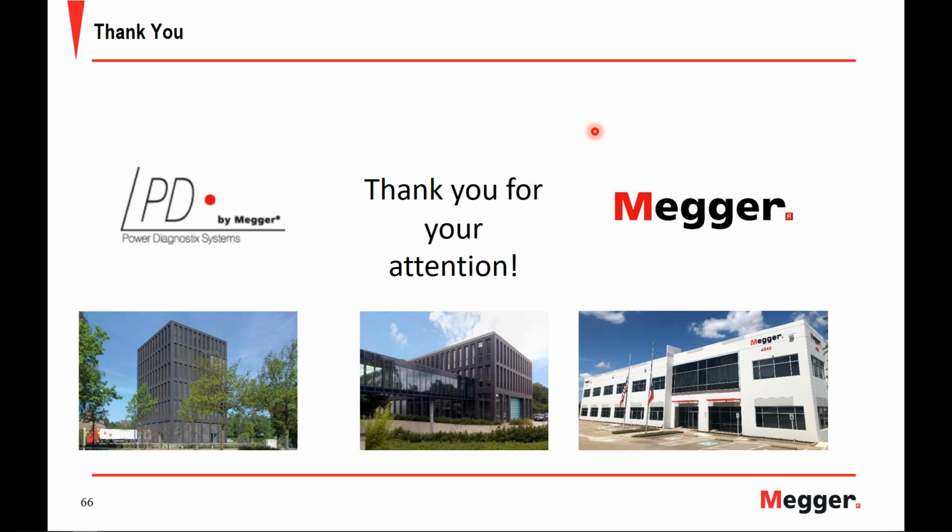Thank you. While I have you, if I'm getting all types of PD patterns in one plot, how can I say which PD is the dominant PD? It's as Charles explained during the presentation. With an offline measurement, you increase the voltage stepwise, and that means you will also have to look at the PD level and pattern proportionally.